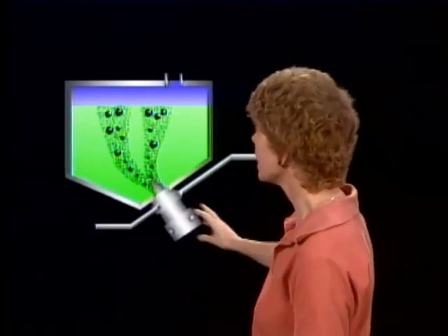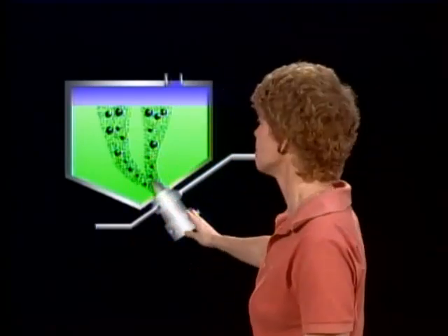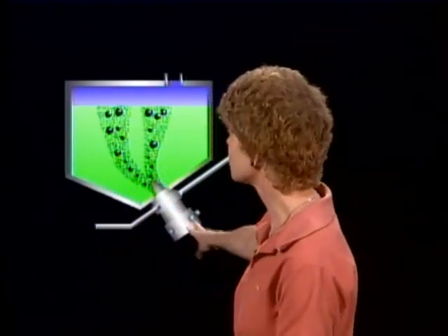How much fuel pressure you've got on the outlet side of a centrifugal type fuel pump is regulated by the pump's design and its own internal clearances. It is not regulated by the speed of the engine, because when you're working with a submerged single-speed centrifugal type fuel pump like this, it's regulated by the pump's design and its own internal clearances. That's what controls the outlet fuel pressure.